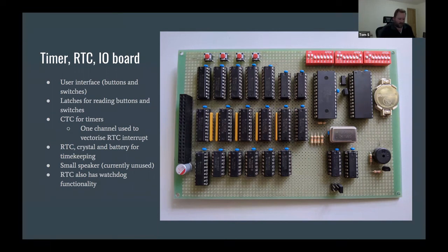And then the switches are used for configuring what's being displayed on each row of the display. So basically, I've used one of the switches, position 8, I think, which is the most significant bit, to indicate whether what's being displayed on a line is a date or a time. So with the switch in the on position, it's a date, and with the switch in the off position, it's a time. And that basically gives you the option to select between 128 different time zones that you could then have in the ROM.